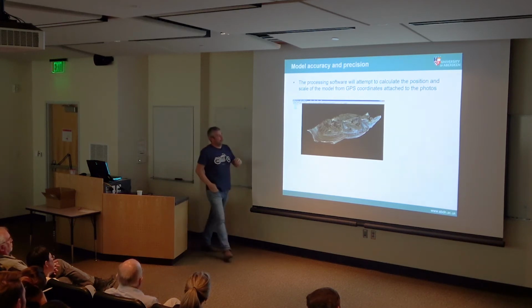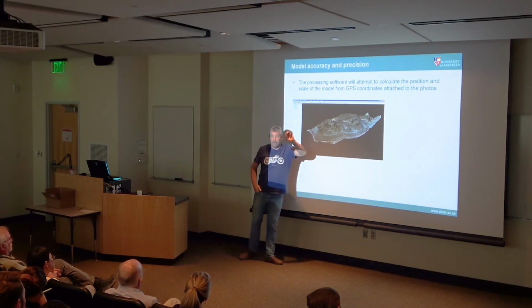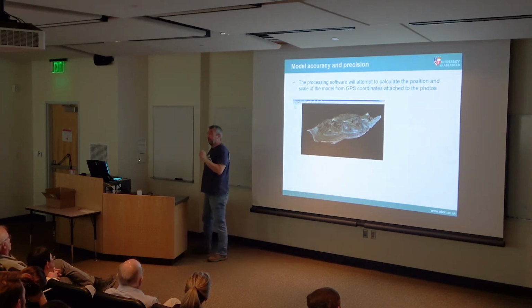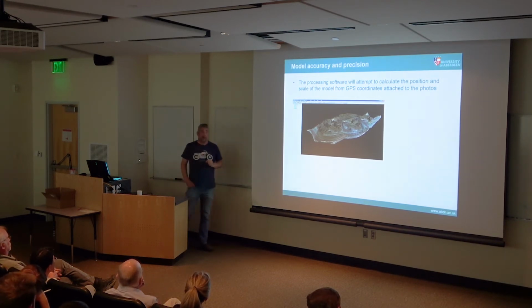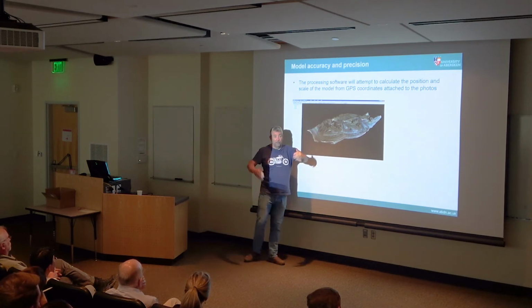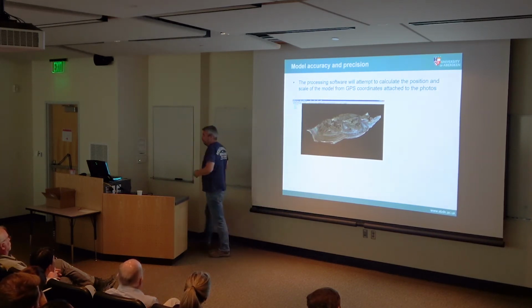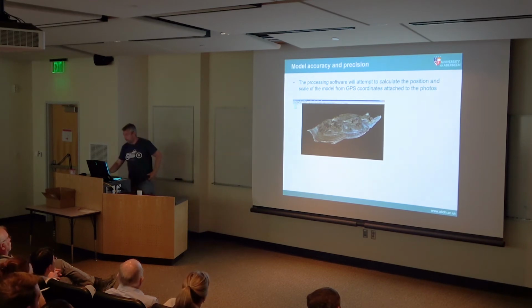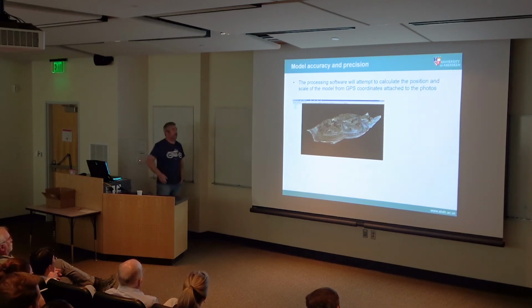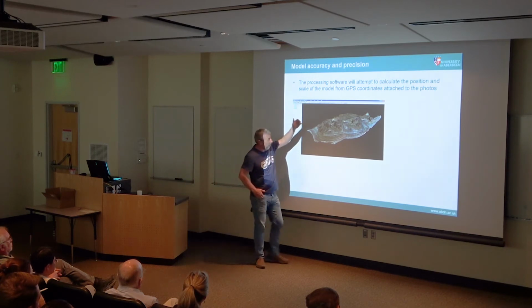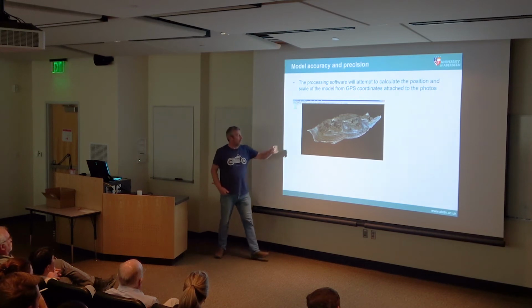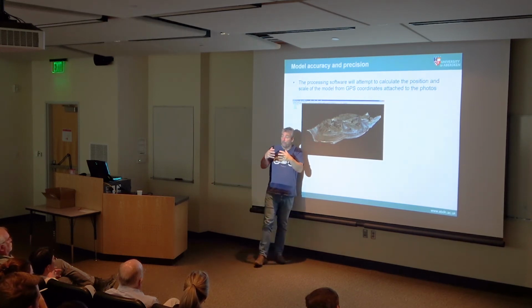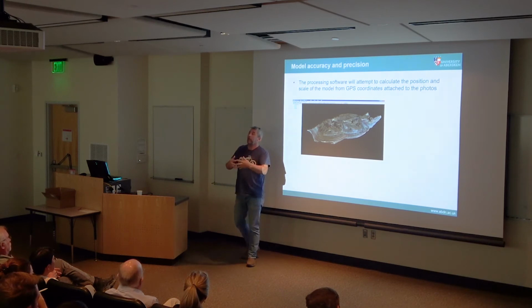But then I went in and I measured about 100 beds in here, and I measured the same 100 beds. And you find out that actually the accuracy, the consistency, is incredibly high. So the models are very accurate, but just the position is not precise. So you can argue about whether that matters. If you're really worried about where it's placing the models, and there are sometimes good reasons to want exactly the right real-world coordinates, then you can put out a bunch of ground control points and process the model with the ground control points in, and it will be super accurate.